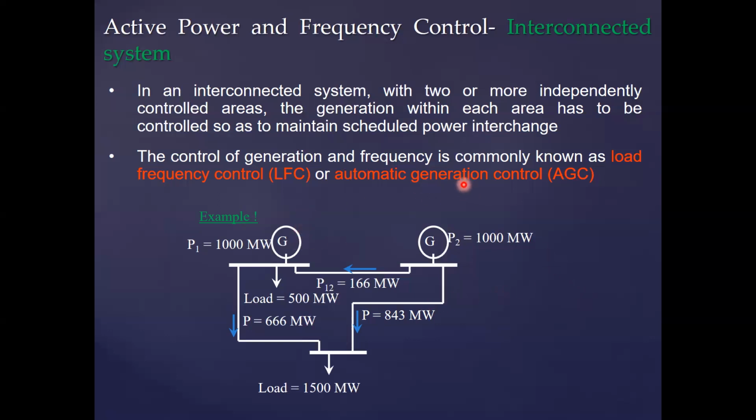We have this generation control, but as I said, the optimal power solution which you talked about, we do it in fact after several time spans. It could be after a duration of several hours, or at least for 24 hours and next for 24 hours, that way. But we don't do the optimal generation scheduling every 5 minutes or every hour.